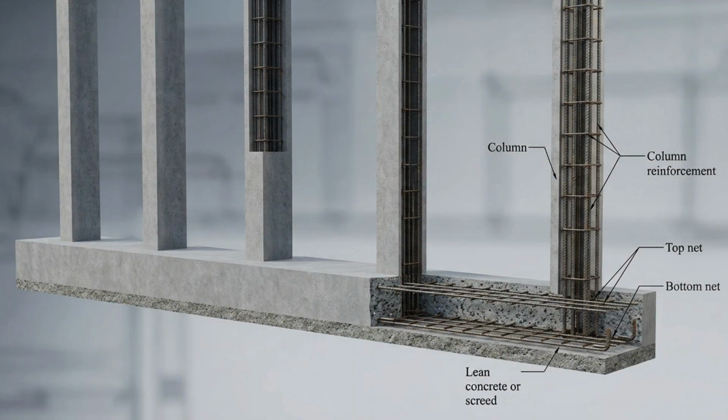Finally, regarding the dimensions of a strip foundation, there is no standard size that fits every project. The width, depth, reinforcement, and concrete grade are determined through structural design carried out by a qualified structural engineer. The design is based on several factors, including the building loads, soil-bearing capacity, number of stories, wall or column arrangement, groundwater conditions, and any additional loads such as wind or seismic effects where applicable.